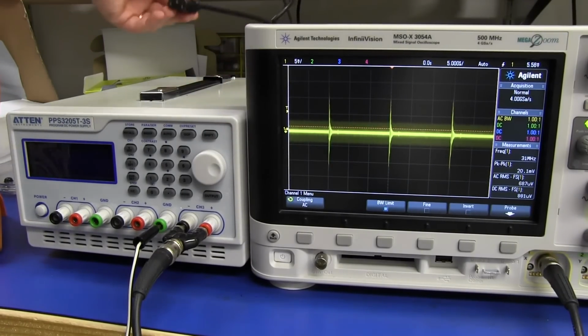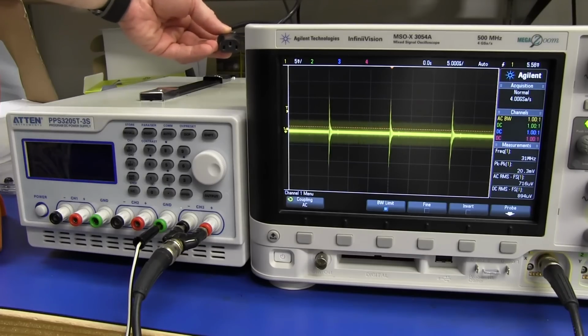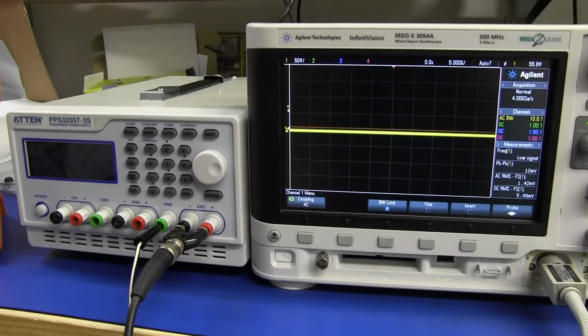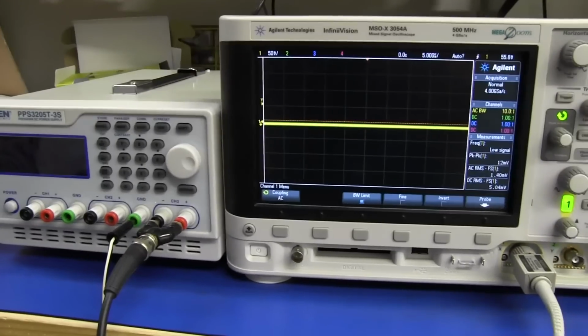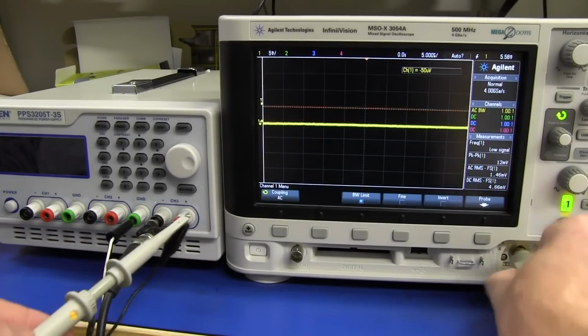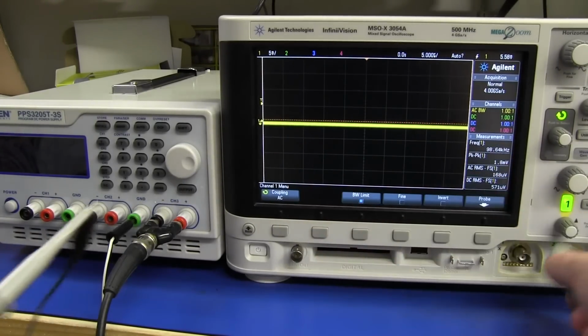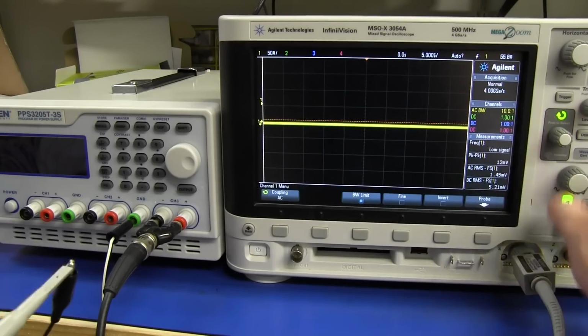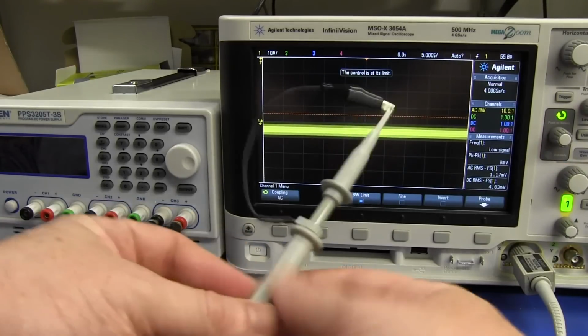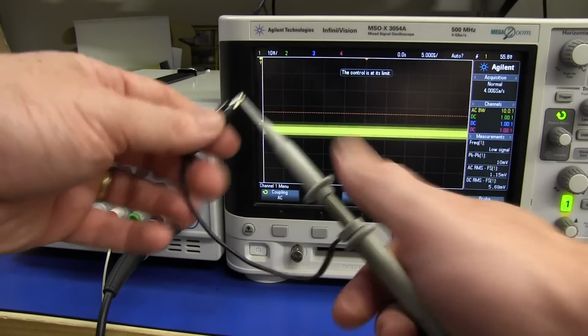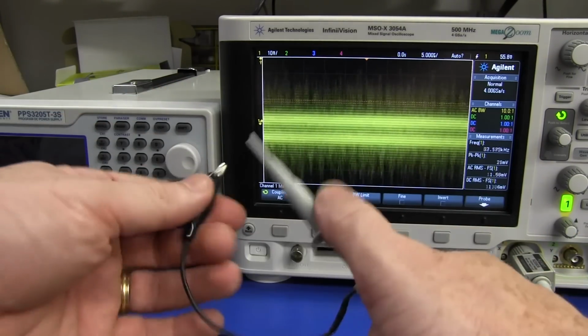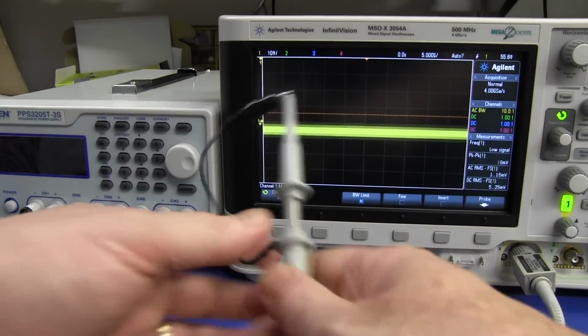Look at that. I just pulled the mains plug and it's still coming through. What do we try next? Well, let's try a real scope probe. I've got my 500 megahertz Agilent scope probe here. It's a real fair dinkum probe. And look, I've even got my antenna earth loop there. And look, we're not picking up anything at all.